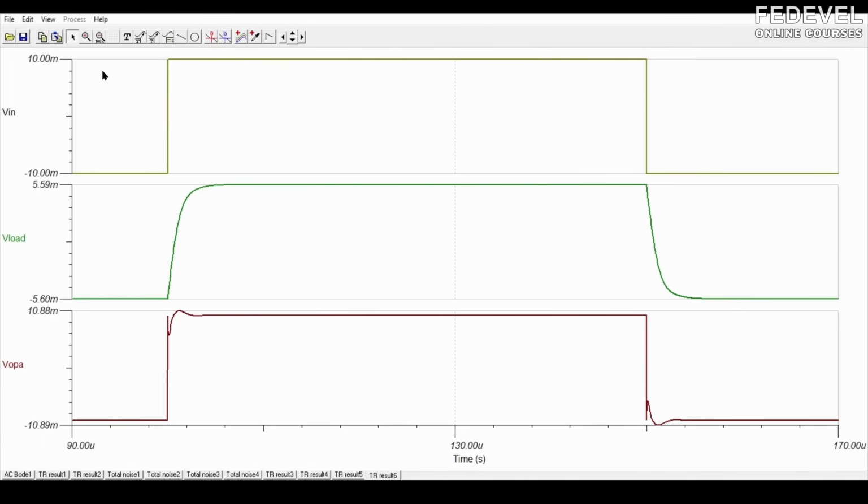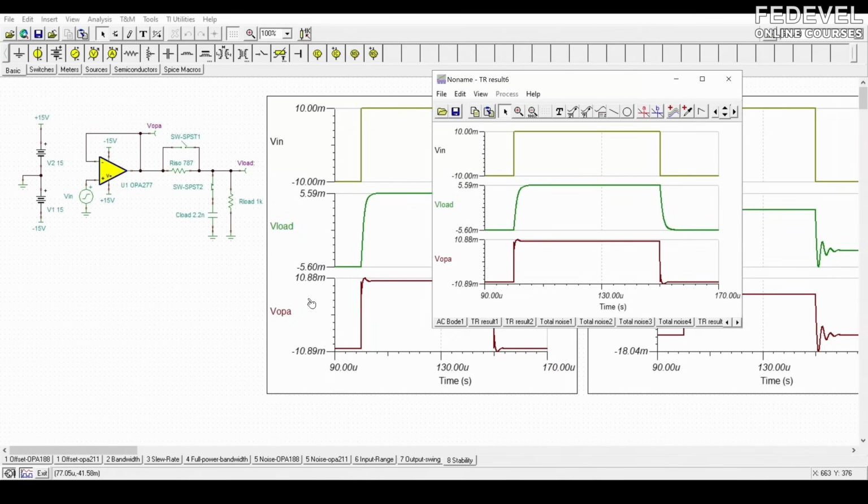And this is a very common problem that we deal with, where people want to filter their op amp output, and they just connect the capacitor directly to the amplifier, and you get this stability problem. Or even sometimes, people know that they can't have a big capacitor on the output of the amplifier, but they're driving a cable, and cables can have a lot of capacitance, and that can cause an op amp to oscillate as well.